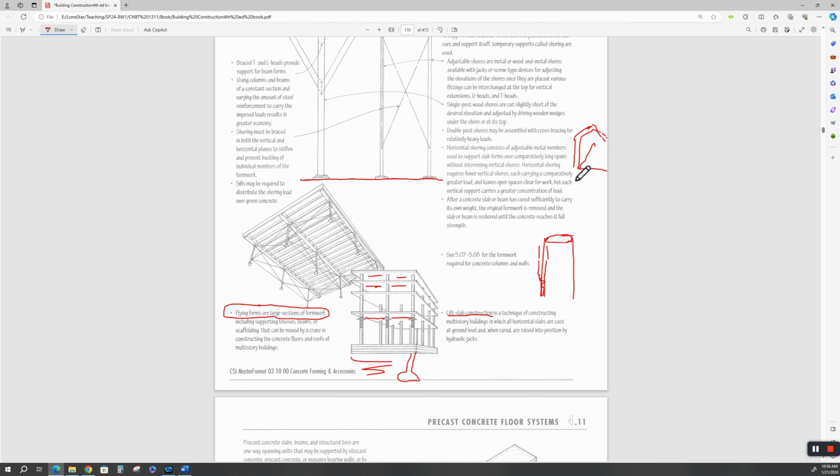And when this reaches minimum strength, there's usually a cutting foot on this because it's sitting on dirt. Then you'll come in here and you'll dig the dirt out from underneath it and let it sink. And this thing will sink into the ground. And then you'll pour another concrete box on top of it. Keep digging the dirt out and it'll start to sink, and pour another concrete box on top of it. It's called caisson, slip forming caisson concrete.